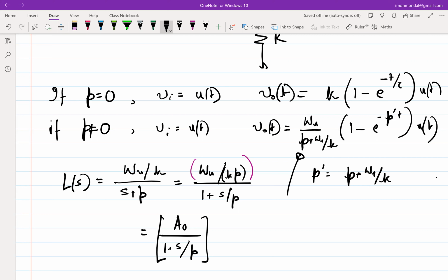Look, loop gain also. So this is not the loop gain now, right? This is the open loop transfer function that degrades at the rate of omega u over s. This omega u over s degradation is consistent with the gain of the integrator if p equal to 0, right? So H is the closed loop gain. The point that I'm trying to make here is that the closed loop gain seems to be following the integrator transfer function beyond omega u over k. Okay.